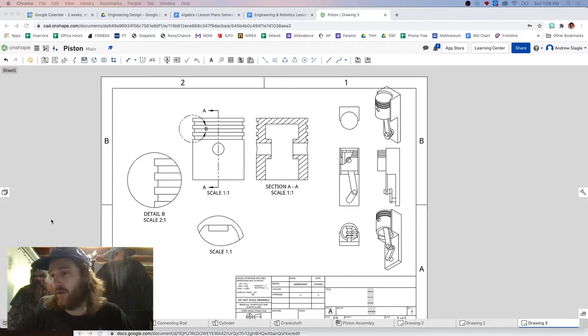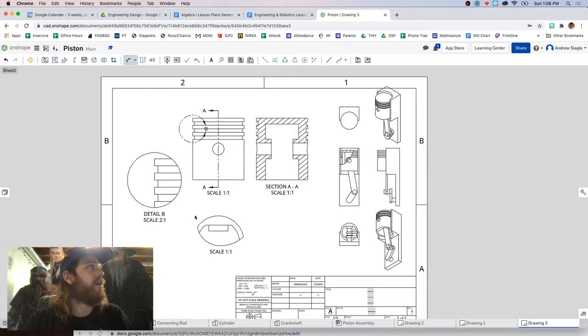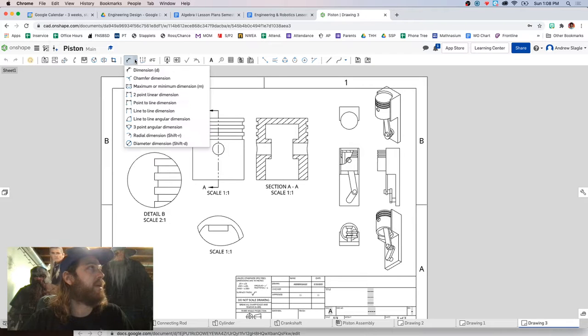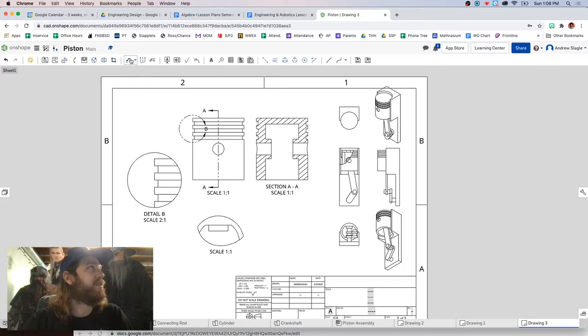Just like Uncle Herbert always used to say, no detailed view is complete without a good amount of detailed dimensions. So that's what we're going to do next. Adding dimensions is actually very easy. There's a couple ways you could do it. You could go into Insert and add a sketch and just show the dimensions that are already there. Or maybe you just want to show some selected dimensions. So you can click on the Dimension tool here, and there's lots of different options for what you can select, but you just select the default Dimension tool. That should get the job done.